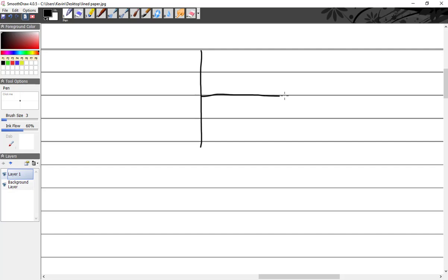To plot an AC circuit, I'm going to look at something like this, where this line right here is the resistance. Up here I would put inductance, and that's my coil, so I'll just put a coil. Down here would be capacitance, and I'll just put a capacitor. All three of these things work in conjunction to give what we call impedance, which is the total sum of all of these things. You have resistance, which comes from resistors, a resistance-like effect that comes from inductors, and something like resistance, but it's not, from capacitors.